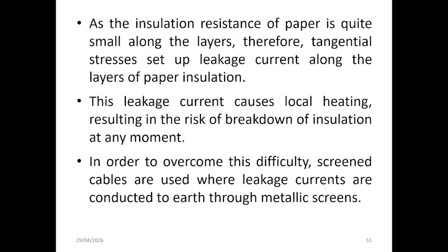Okay, this slide explains the limitation of the belted cable at higher voltages and the need for improved designs. Since paper insulation has a relatively low resistance along its layers, tangential stress can create leakage currents through the insulation.